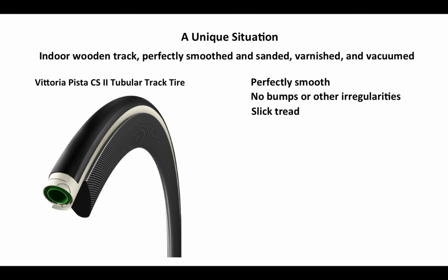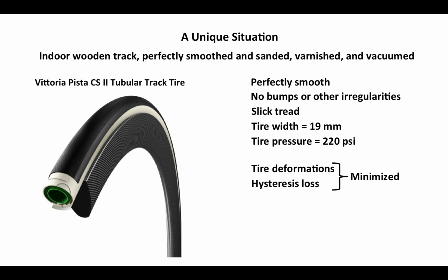I have a slick tread on the tire, a very narrow tire, only 19 millimeters, and I pump it up to a whopping 220 psi. The combination of all of this gives us very little tire deformation and hysteresis loss. Both of those are minimized.